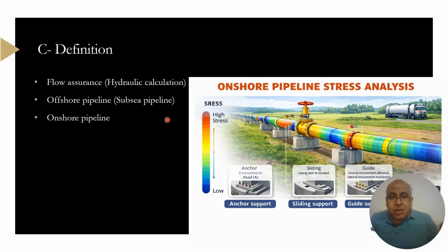According to the level of the water we have, what about the pressures that will be applied, the bottom stability, and the effect of the mattresses? How can we design the mattresses? How can we design the coating for the stability of the pipeline itself? All this should be discussed. We must avoid buckling and avoid propagation of the buckling when designing the offshore pipeline. We design the offshore pipeline to carry the load and also for the stresses during installation. So we have more than one mode of failure.